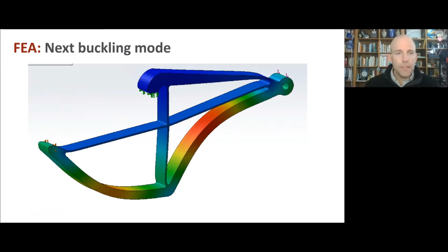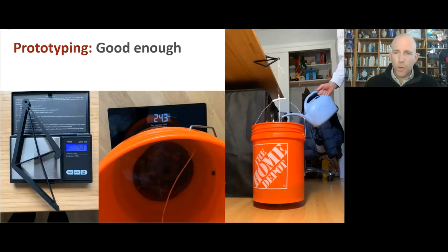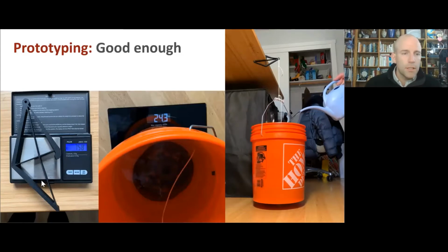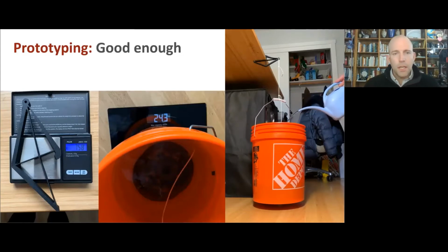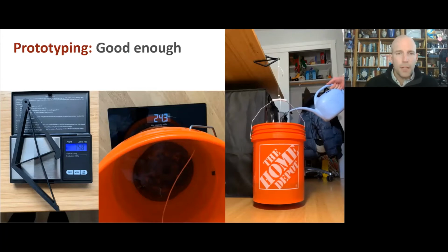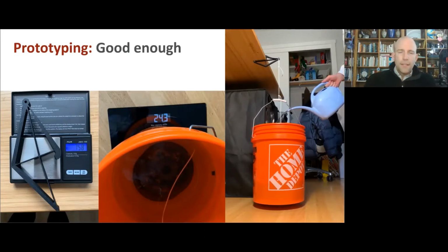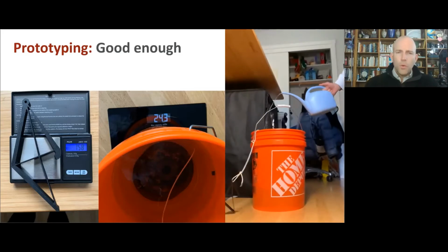And when testing this, this is what it looked like. So here we have the final component. This one's about 7.6 grams, and it failed at about 24.3 pounds. And here you can see that element that is in 3-point bending, ooh, yeah, that deformed a lot more than I was expecting in the real part. It may have something to do with the way that I set up the print, the way it was sliced.